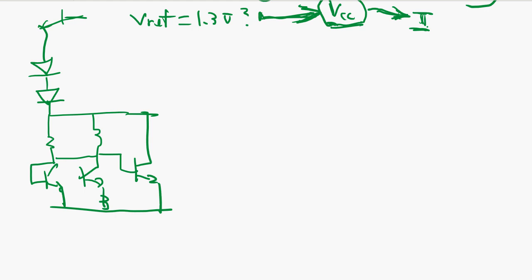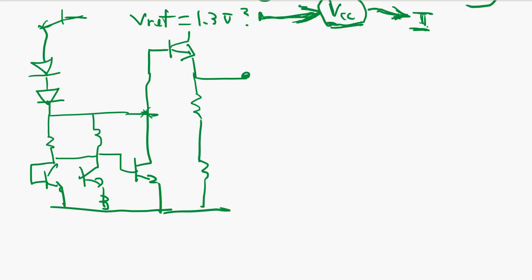From here, actually you don't connect this. You go up and make it the output transistor. This is the output. And you divide this voltage to the ratio you want and give a feedback to this guy. Okay.